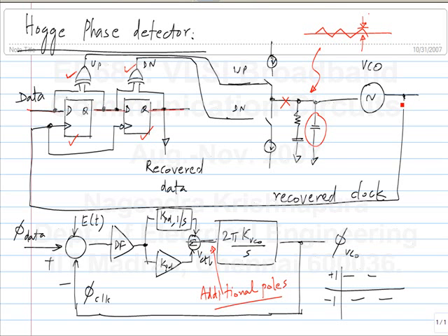So the disturbances may come because of steady state disturbances on this, or maybe, for instance, we assume that this capacitor holds charge. So in some architectures, in some cases, the capacitor may have a leakage, or maybe there is some other part of the circuit that has leakage. Okay. So no capacitor will hold its charge indefinitely on a chip, right, because there will be leakage paths. So that can be modeled by something like this. This current may be of the order of nanoamps or whatever it is. So there also, what happens in this case, the voltage will keep steadily decreasing.